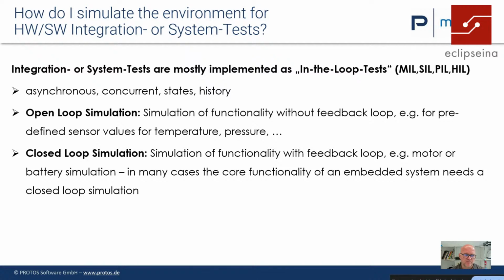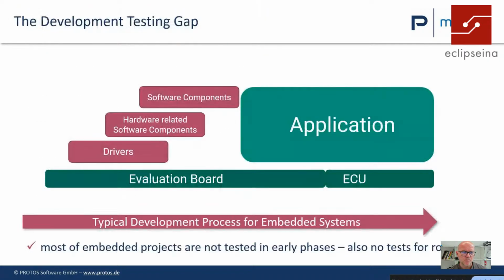Most interfaces can be simulated open loop. Usually the core of your application needs to be simulated closed loop. If you have a motor controller, you need a closed loop motor simulation.